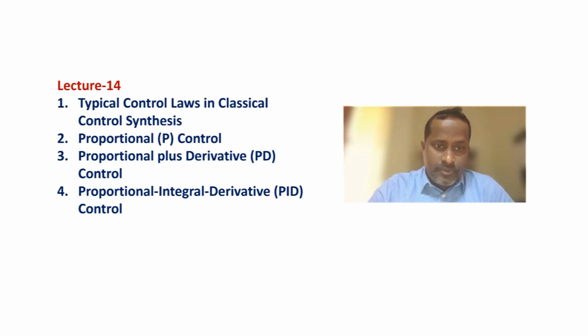And then we'll move to PID control, where we'll be adding the integral part to the control. Basically, if there are disturbances acting in the system, and due to that disturbance there is a steady state error in the response, through the help of integral control that steady state error can be mitigated over time. Then we'll conclude the lecture.